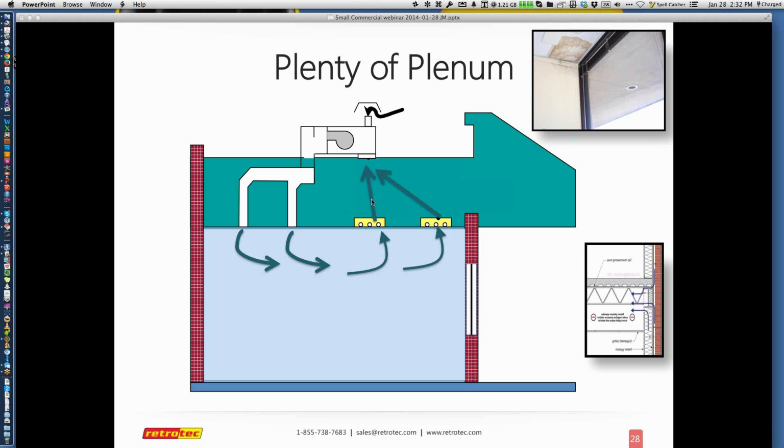Most commercial structures are moving away from that, but as you saw in the numbers earlier, there's a huge amount of existing structures that may fit this model. I bet as you drive anywhere today, you'll drive past 1 or 2 of these types of structures. The issue here is that this air that's running wild up in the upper section is exposed to areas that become outside walls or outside ceilings that are part of the walkway. So I could easily have, with can lights or other penetrations, hot, moist air that comes into these sections.